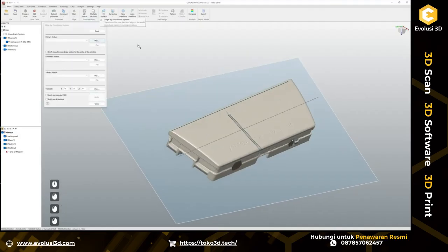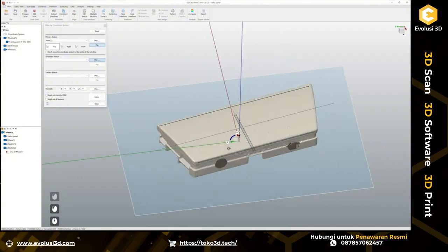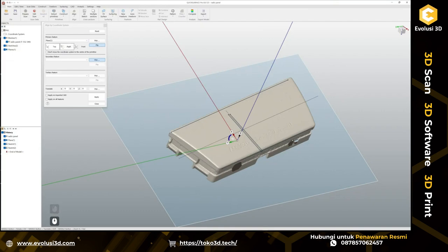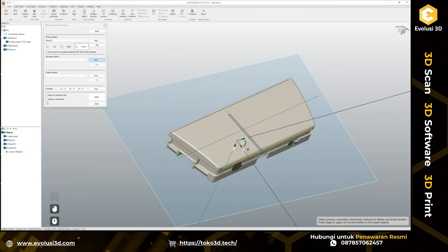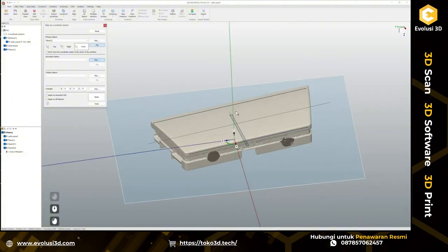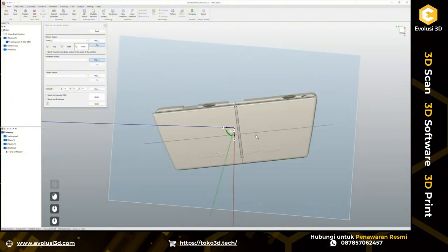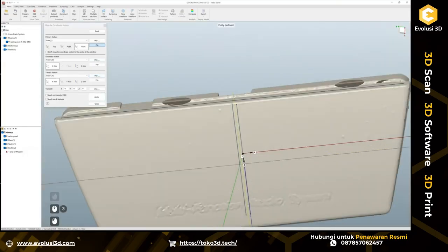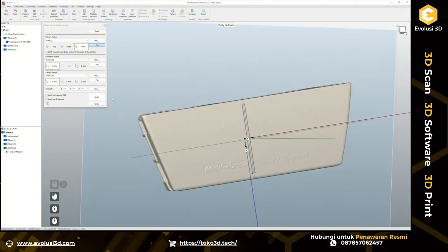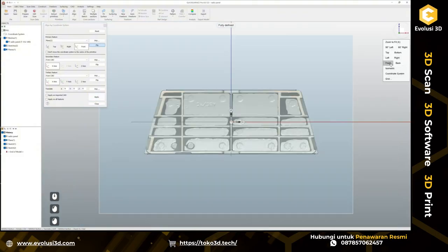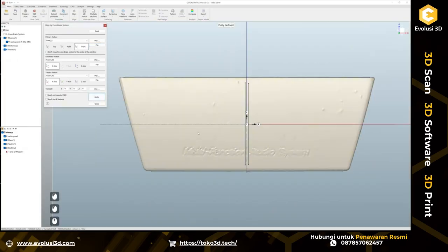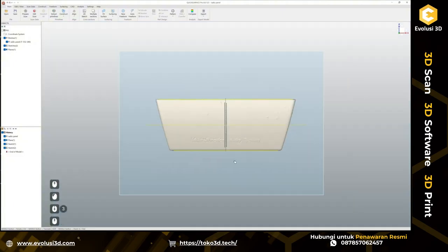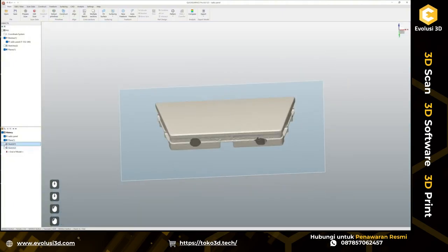And let's go to align by coordinate system, select plane, let's flip it. But this is not top, I want this to be front. Flip, good. Next one, I guess this one, and the last one, this middle line here. Okay, should be great. Let's hit apply, front. Okay, we need to flip it. Done. Looks great. Close the dialog box. Now I can hide all of this.